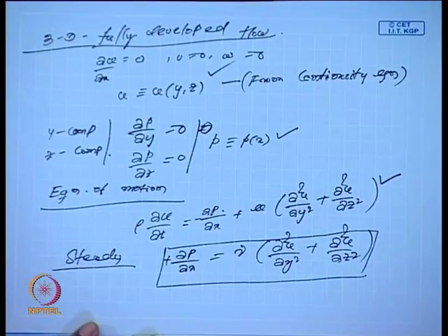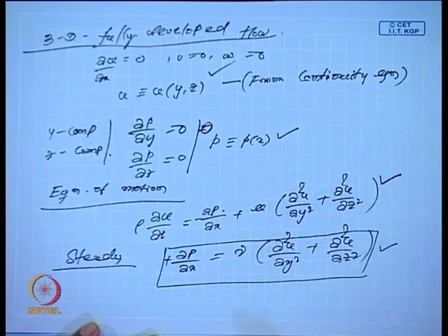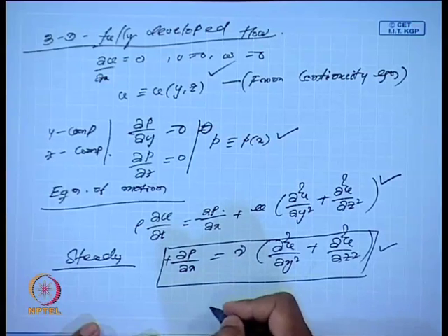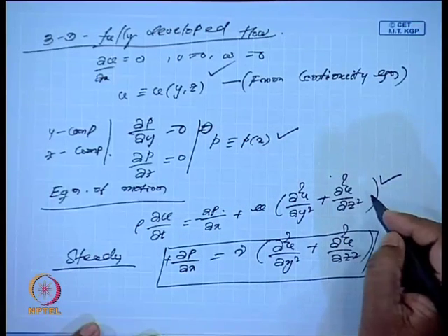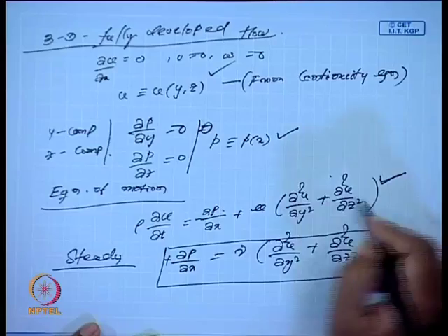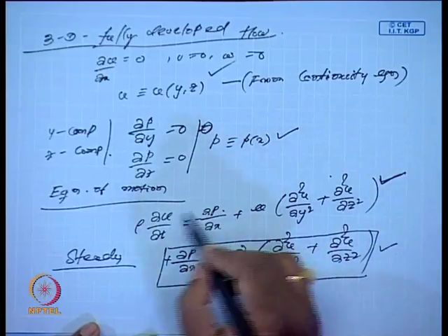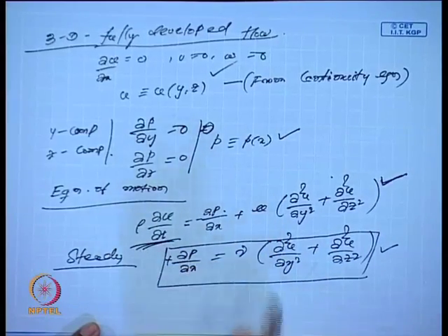So, this is the general form, and here again we need to prescribe the wall boundary condition. To solve this equation as a steady problem, we only need the wall boundary condition. If we want to solve the transient problem, then apart from the wall boundary condition, we need one initial condition to take care of the transient part. So, now we will go to simple flow problems one by one.